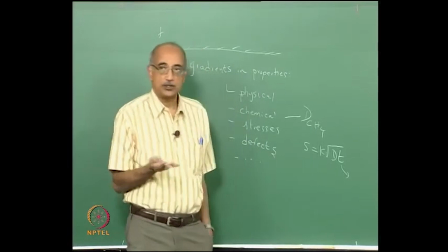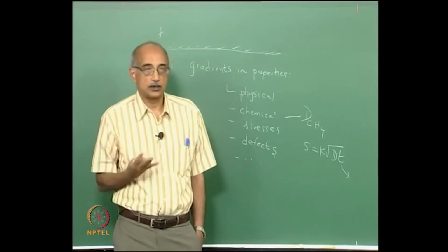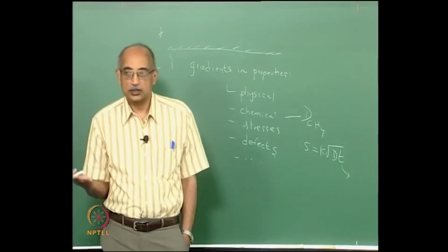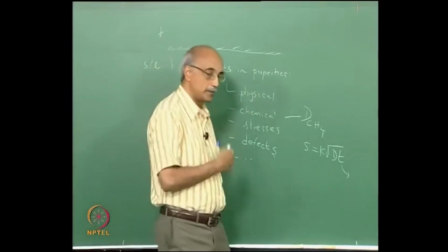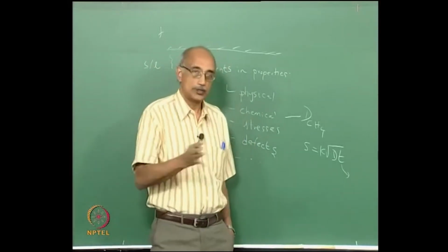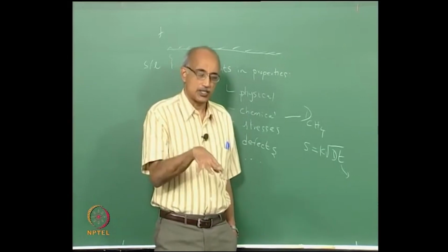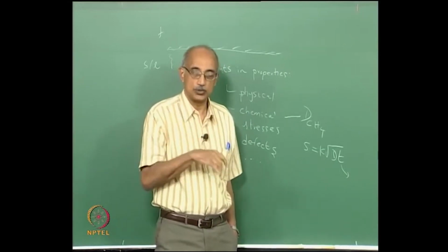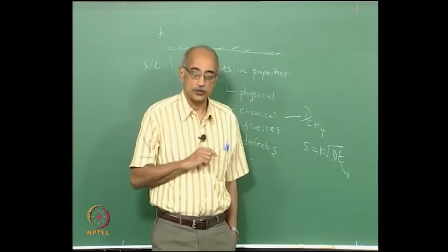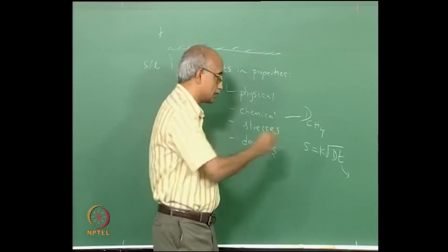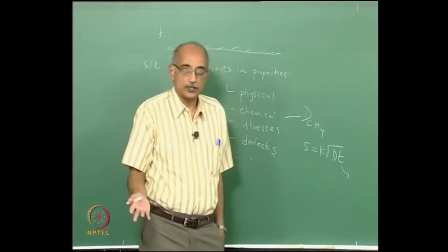Another example would be nitridation. Again, you want to add nitrogen to an alloy material. This is typically done by pumping nitrogen gas over the alloy under pressurized conditions in order to improve diffusion rates and diffusion coefficients, and you will again see this type of behavior. It is basically a square root dependence.